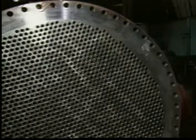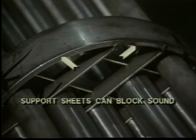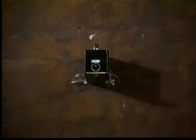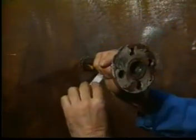In some exchangers, if sound does not travel to the far end, both ends should be tested. The tone may also be blocked by baffles or support sheets. If more sound is needed, you may use more tone generators with existing fittings in the central area of the heat exchanger. Or you may create additional fittings for testing purposes if your company's policies permit.